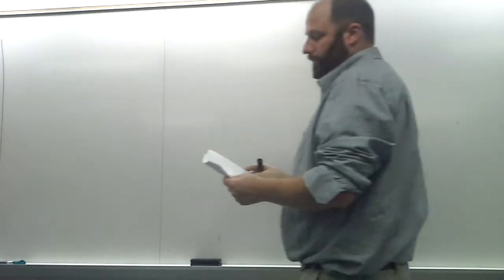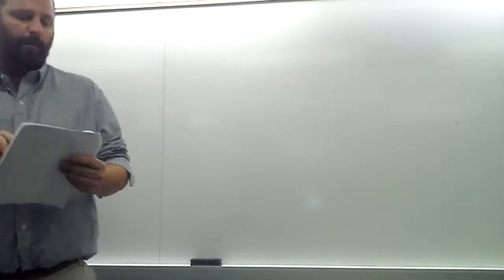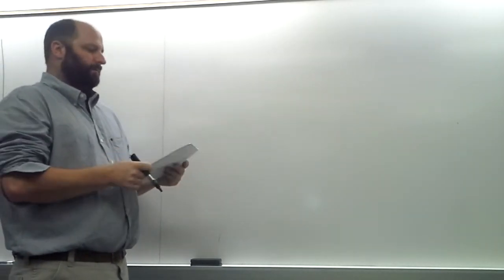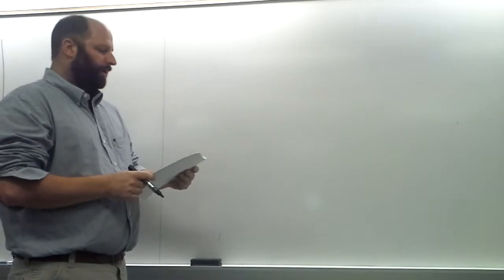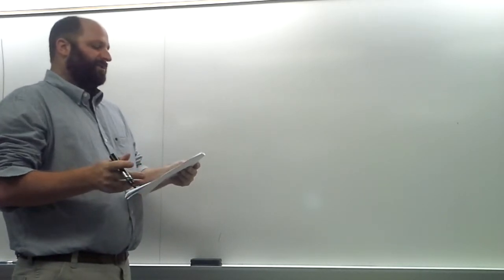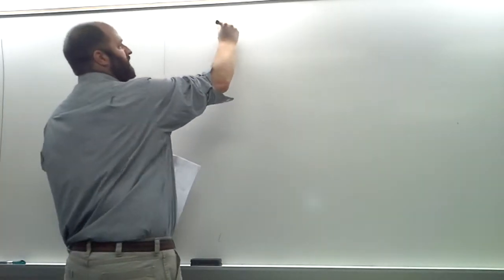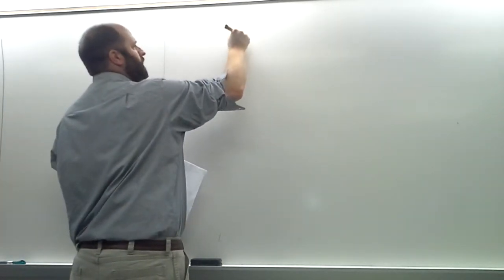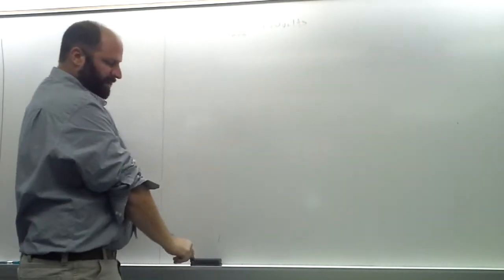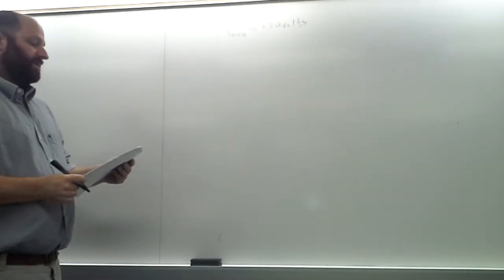So, I'm going to pick up on your homework here. We're going to start talking about number 5 under the AC circuit transformers induction homework. And number 5 is about AC voltage, because it even mentions the word RMS. It says the RMS voltage is 120 volts, and they're talking about the voltage of these power outlets here. What is the peak voltage?